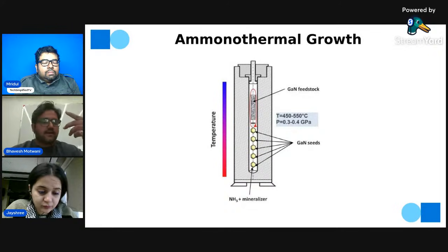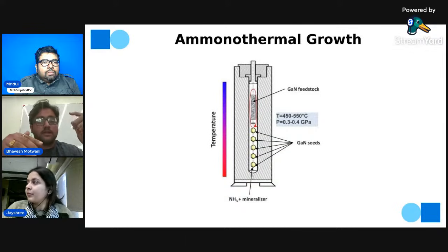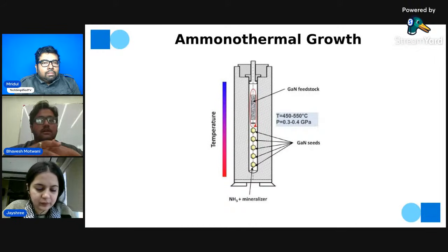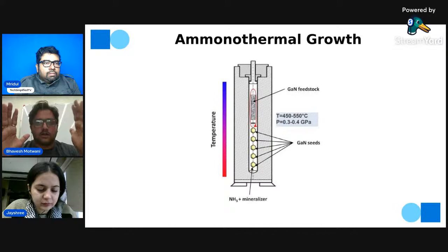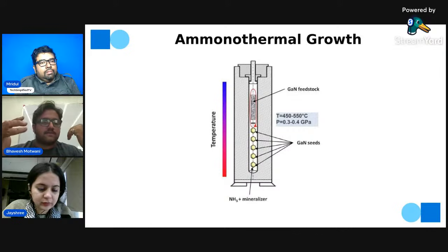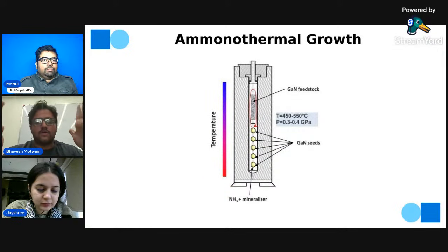So in CZ and FZ, we can understand how silicon is made. In the ribbon method, we can understand how, just for solar wafers, we can produce them in a very easy manner, with a very low amount of wastage compared to the CZ method, because CZ requires slicing and polishing also. Instead of that, we get a direct wafer out of it with very little wastage.